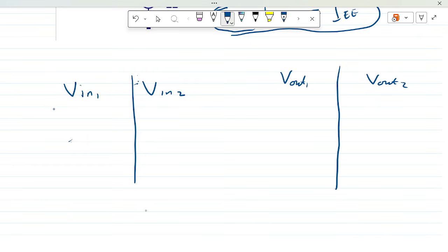Okay, so Vin1 went up by delta V, and the differential signal should be such that if the output wouldn't reject this change, then Vin2 will go down by the same delta V. We just realized from the common emitter stage that if the voltage goes up, the output should come down, and the output would come down by the transconductance of the device times the change in the voltage.